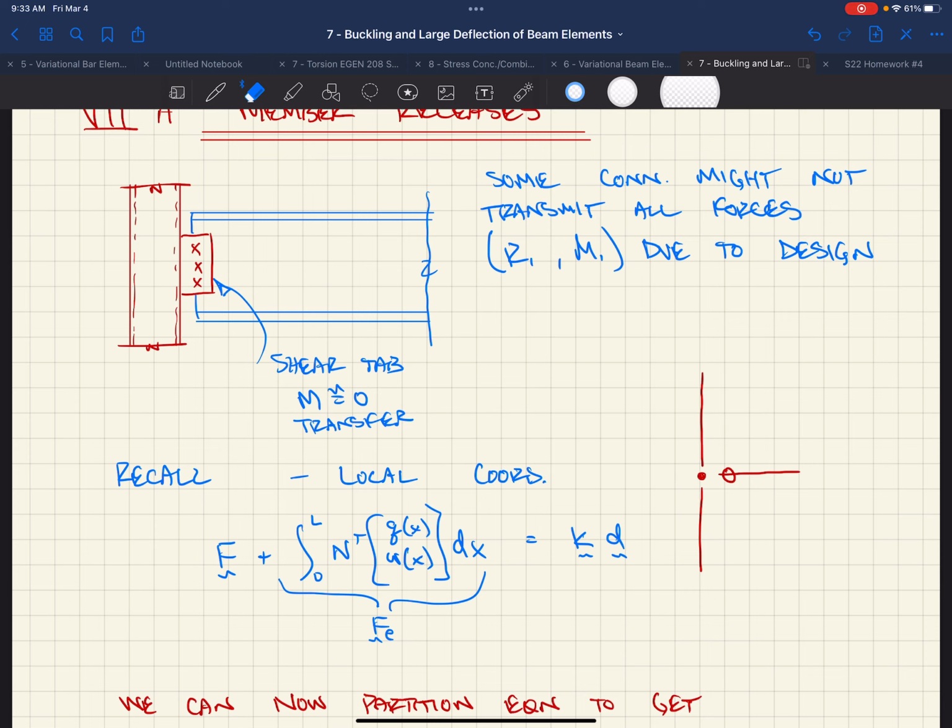So I'd argue if you did anything, it should be just modeled. You should just model it. Take the component that gives you the greatest in-plane stiffness. So for a wood diaphragm, it'd be the sheathing, right? You could model that sheathing, whether it's 5/8, 3/4, whether it's the roof or the floor, right? And you could model that, and it would give you a pretty good idea of how that load is distributed. In the end, it's a guess, again, right?